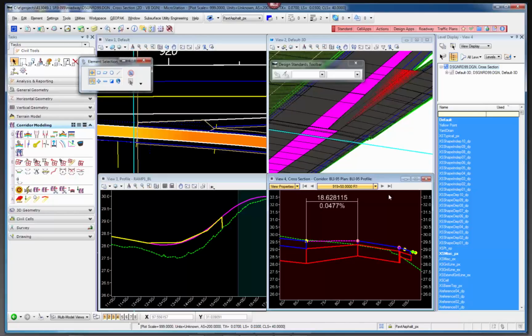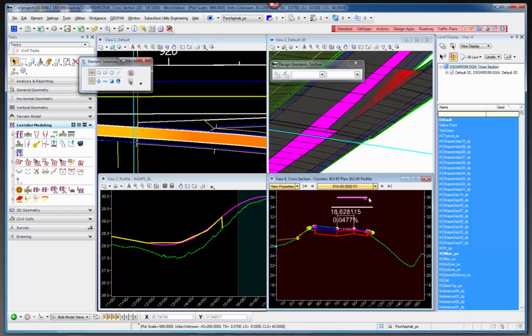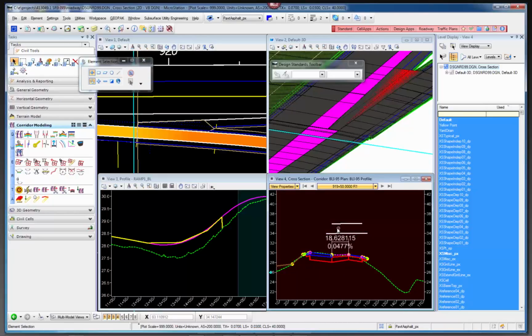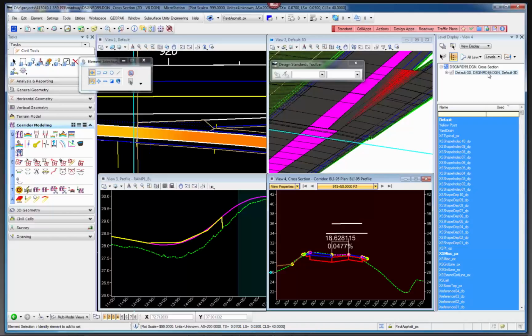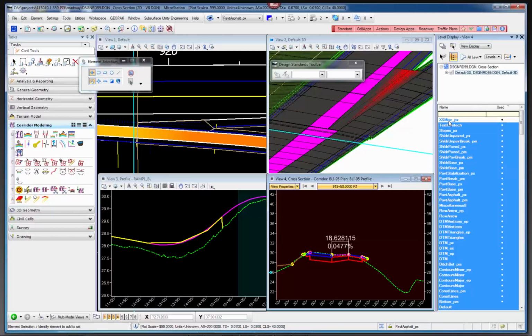Yes, these trigger lines, what I call trigger lines or search lines, someone asked the question, how can you turn these off or basically idle them? Essentially, it's in this view right here. If you look at this, you just turn this off, which is the cross-section miscellaneous PX level. Because in our templates, we use a specific cross-section miscellaneous component that all you have to do is turn that off.